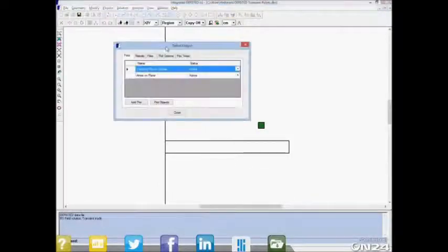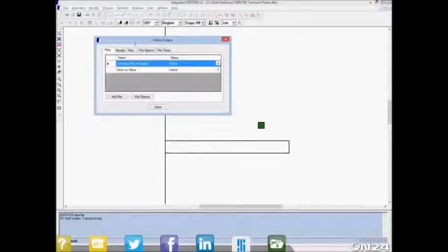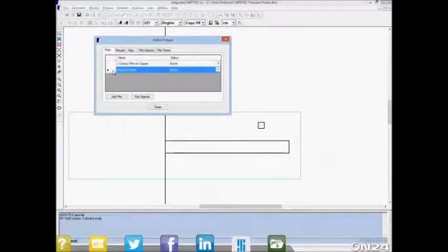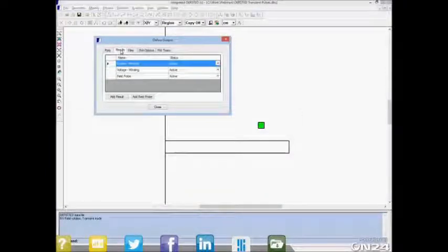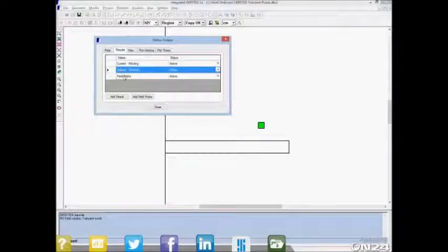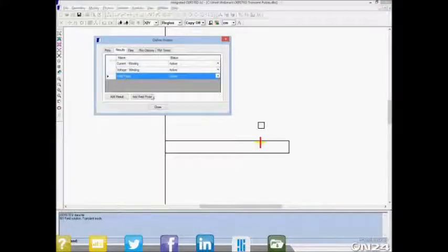So what is being asked for in this model is two different types of plots. There is a contour plot of the current density that's being asked for on the piece of copper, and an arrow plot of the B field that's being asked for in the surrounding space. Furthermore, three different results are defined. One is the current that flows in the winding, the other is the voltage on the winding, and the last is a field probe, which, as you can see, is right around where the current induced in the plate is going to be the highest.